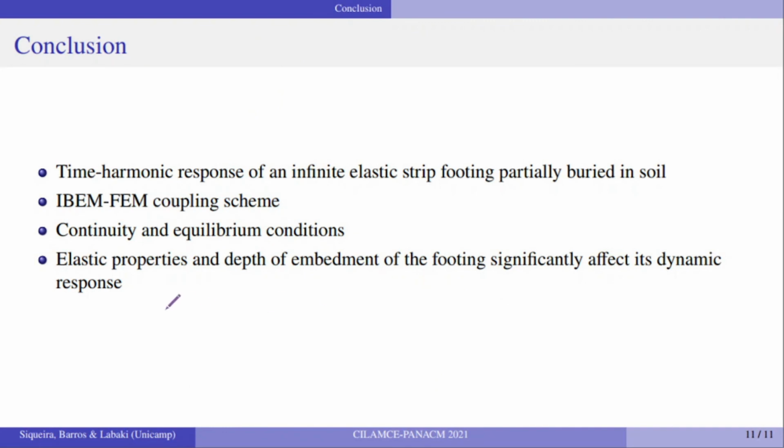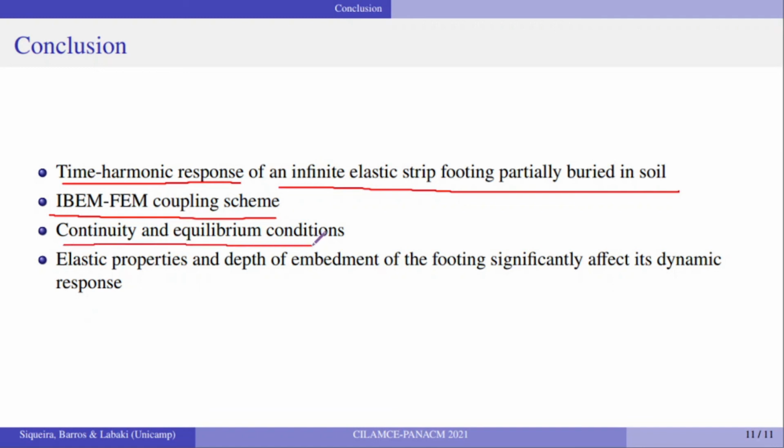This paper presented a model of the time harmonic response of an infinite elastic strip footing partially buried in soil and subjected to external loads. An IBEM-FEM coupling scheme was proposed to model this foundation-soil interaction problem. The condition of perfect bonding between structure and soil was modeled by establishing continuity and equilibrium conditions throughout the soil-foundation interface. Results showed that the elastic properties and depth of embedment of the footing significantly affect its dynamic response.